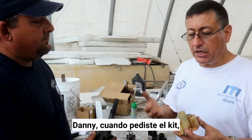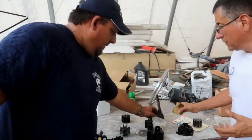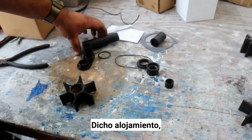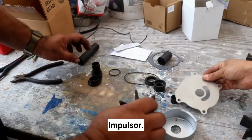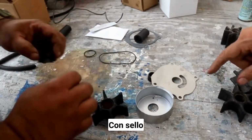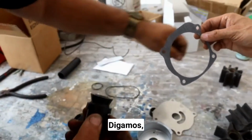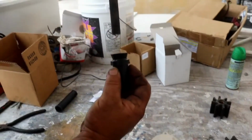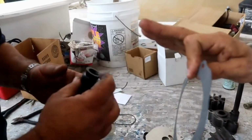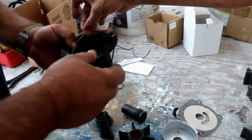Danny, when you order the kit, depending on the model, what do you receive? Well, here's one kit that we have complete. It comes with the housing, the wear plate, the impeller, and then the seal we were talking about on top. You have the seal that goes on the water tube. So if your water tube is coming from the engine, it would go in there. And you have to put grease. Always. Marine grease. And so here's the deal: on the housing, the gasket goes here.